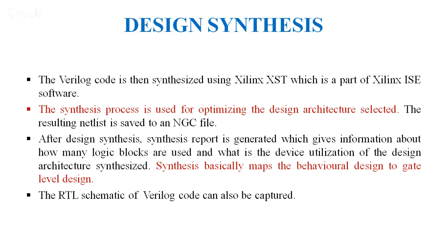There are multiple logic blocks available in FPGA, so how many blocks are used in our design, and what is the device utilization of the design architecture. Basically, synthesis maps the behavioral design to a gate level design. So our behavioral design, which we wrote in code, is converted into a gate level design. We can capture the RTL schematic of the Verilog code which we wrote in Xilinx ISE.